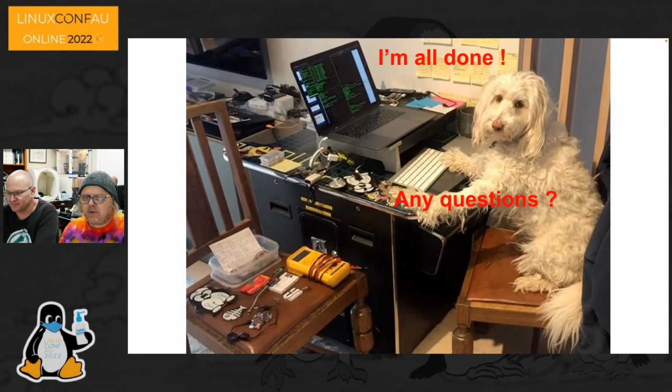In a situation where we have lots of parallel inputs, where we would need to do signal processing, that's a classic use for an FPGA. It's one thing to look after a small number of inputs through a microcontroller, but if you had like 100 signals you need to look at simultaneously, then an FPGA would be ideal for that.